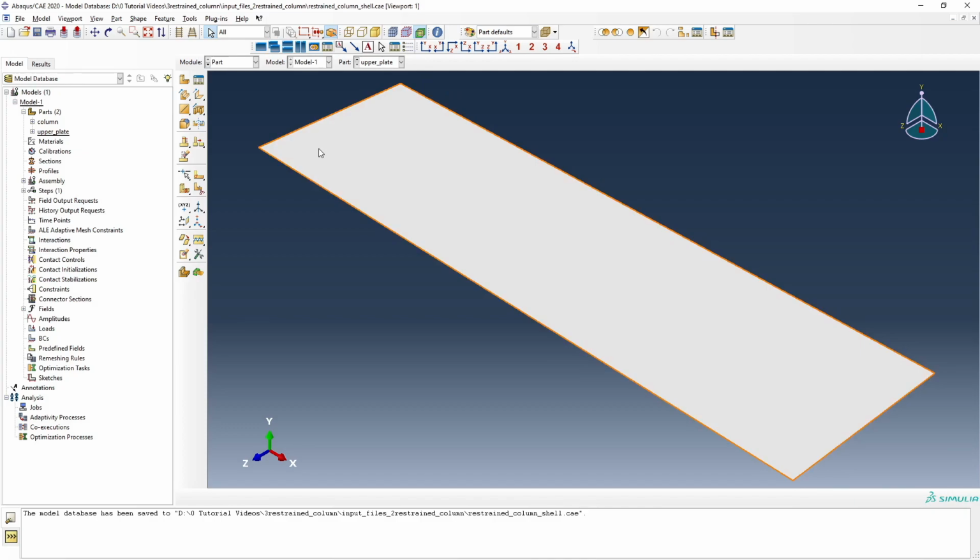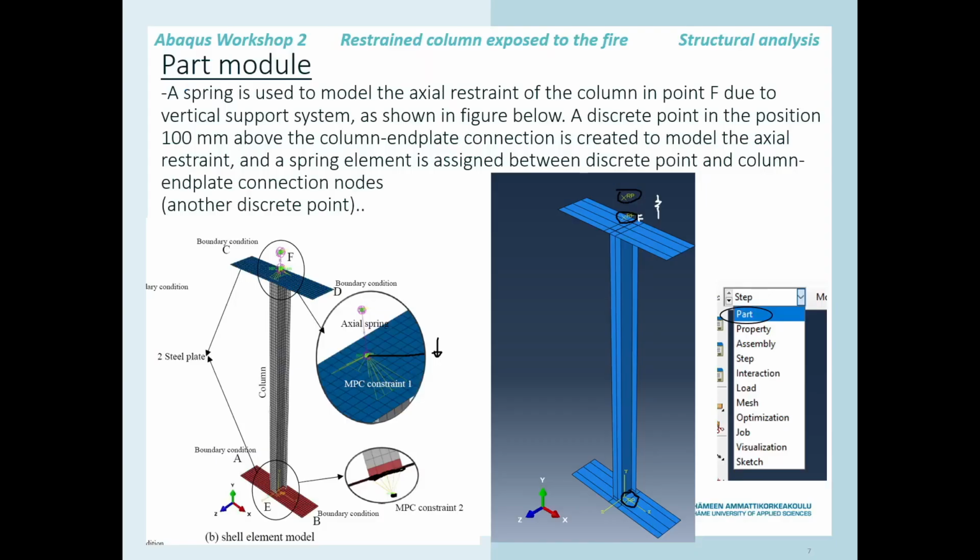And now we will use this partition of the face in order to make the assembly procedure easy in the assembly model. So we will make our partition in such a way that it is easy to apply the connection between the I-beam, I-profile cross sections and this point.